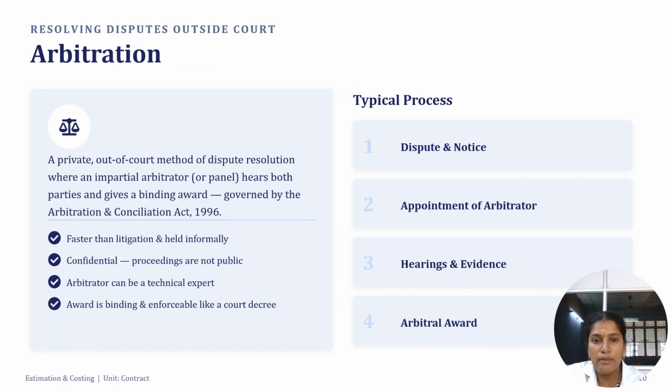Next is arbitration. Arbitration is nothing but, if both parties, the owner and the contractor, have a problem, such as labor or insufficient material, or they are delaying the project without considering the time, whatever it may be, some disputes may arise between the contractor and the owner. So we have to appoint one neutral, private person outside the court. We arrange a third neutral person to solve the dispute. That third person is called the arbitrator. That process is called arbitration.